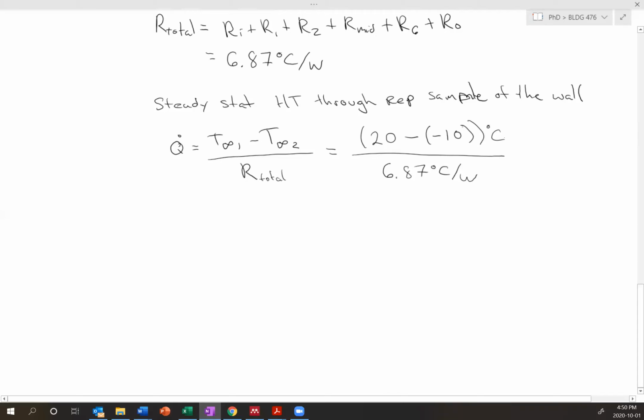And once again, I actually don't particularly like the way they're doing their units here. I prefer to call this a delta degree Celsius. I think it's a little clearer. And just to expand on that a bit, the increment of 1 degree Celsius, so a delta degree Celsius, is equal to the increment of 1 degree Kelvin. But something in degrees Celsius does not necessarily equal something in degrees Kelvin.